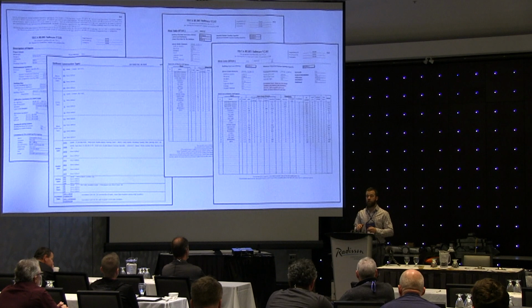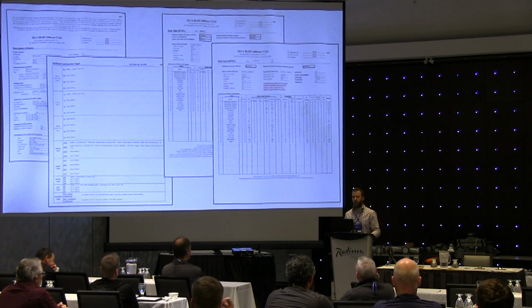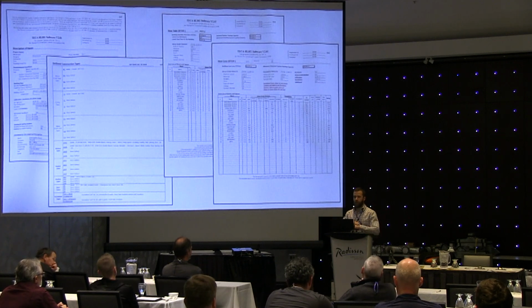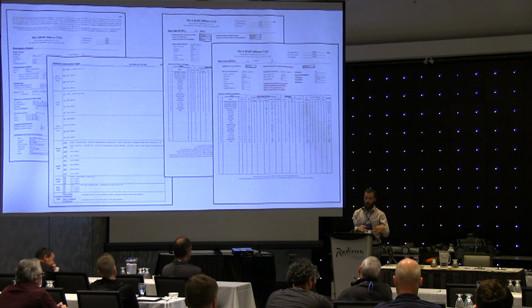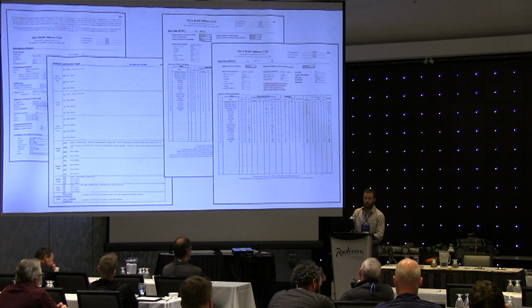That is totally the responsibility of the user. We are not telling you anything about what your insulation has to be or should be. That's up to you. A contractor might have a builder they work for, and the builder's going to code minimum. So you look at the software, the region: climate zone 5. You go to the BC Building Code for code minimum R values for windows, walls, doors. Everything comes from there. Does that answer your question?